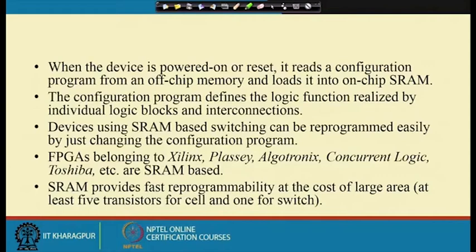Others are also there, so they are also used in many applications. SRAM provides fast reprogrammability at the cost of large area. As I said, the reprogrammability becomes very easy, because you can very easily change the configuration program. However, the area occupied is more, because each SRAM bit will require 5 transistors. So if I have say 10,000 programmable points, there will be 50,000 transistors just needed